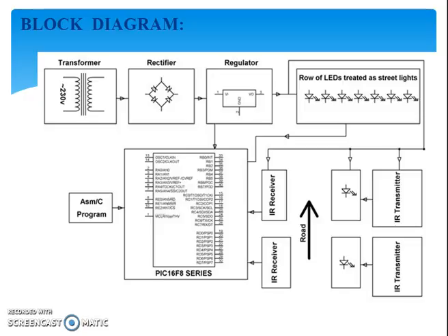The real-time clock IC used is DS1307 which is I2C compatible. The real-time clock has 8 pins. Pins 1 and 2 are connected to the crystal oscillator, 3rd pin is connected to the battery, 6th pin of the RTC is connected to the PC5 pin of the microcontroller, and 5th pin is connected to the PC4 pin of the microcontroller.